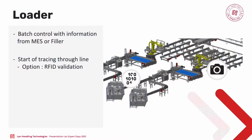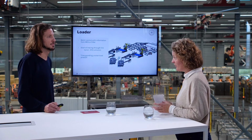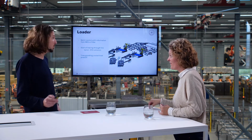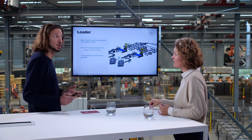And last but not least, we also check if the product that's inside the loader is not there too long, because it's unsterilized product and it has to be inside the retort within a certain amount of time. So we can give a pop-up message on the screen if the product is almost at that time. But why are we exactly doing that? Because the products are being filled, and what happens if they are not on time in the retort? Well, the product needs to be in time in the retort to make sure it's sterilized soon enough.